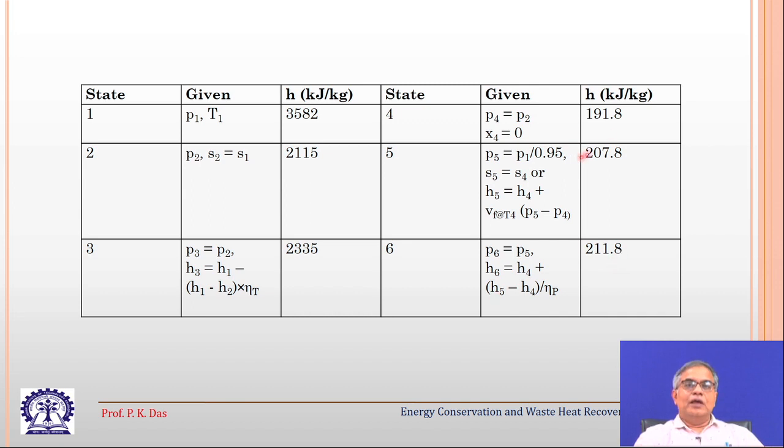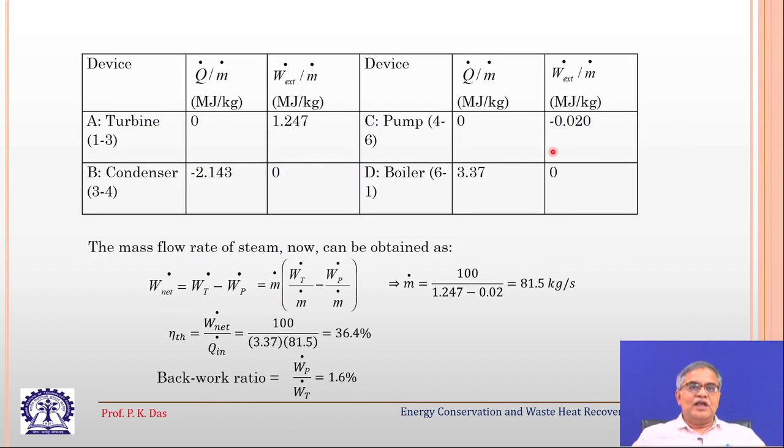So, here you see this value H5 is less than H6. The difference between H5 and H1 gives the ideal amount of work done, and H6 and H1 give the actual amount of work done, and the actual amount of work will be higher because of this irreversibility. These are the points just to remind you of what we have done earlier in our thermodynamics. Okay, let us go to the next slide.